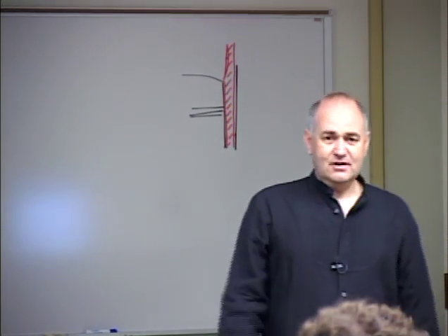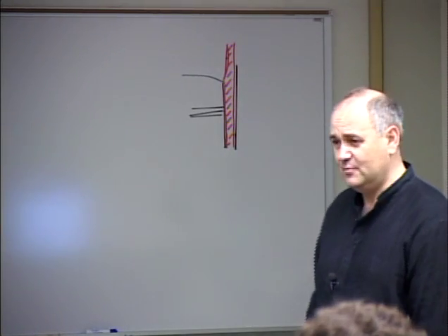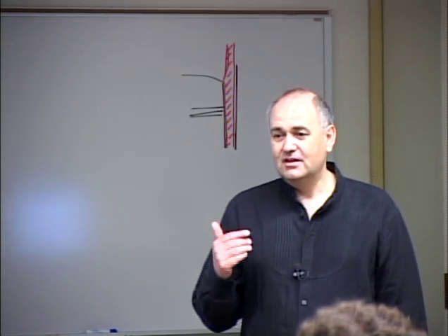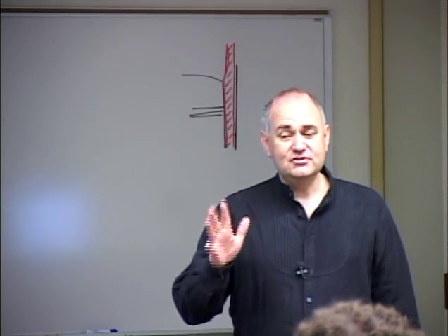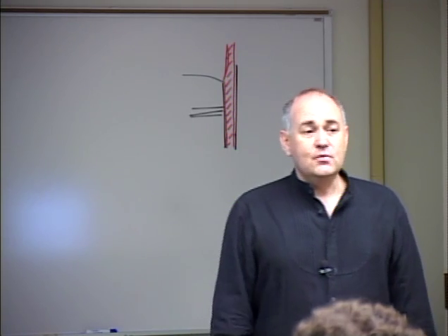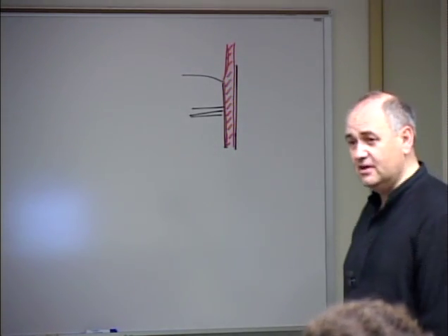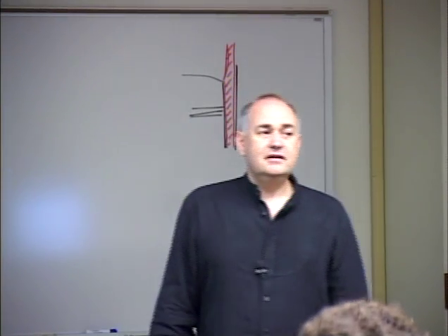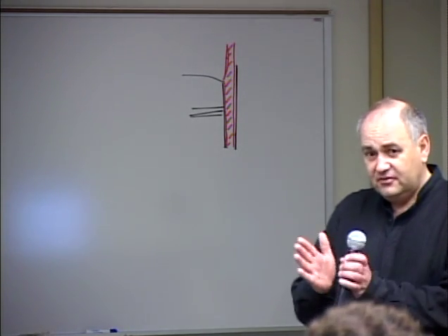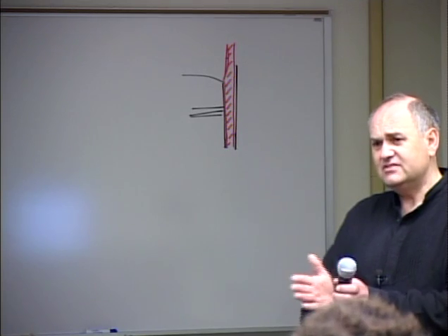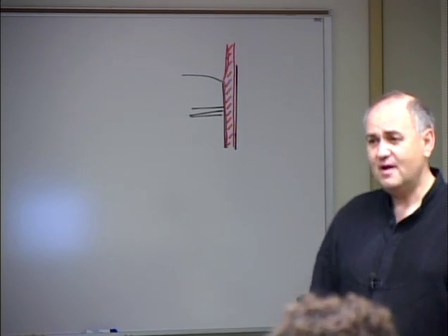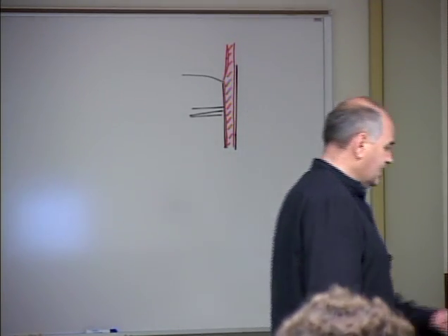Oh, well, one thing is that it would evaporate, but another thing is that it's not viscous, but what you really mean is it does not wet the wall, right? This is what you were thinking, because actually we want a fluid which has low viscosity. So considering viscosity, water would be better than oil, because oil makes the two surfaces stick more than water. However, with water it would be a problem to create the film.